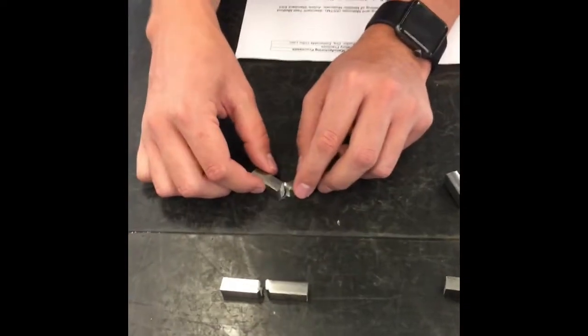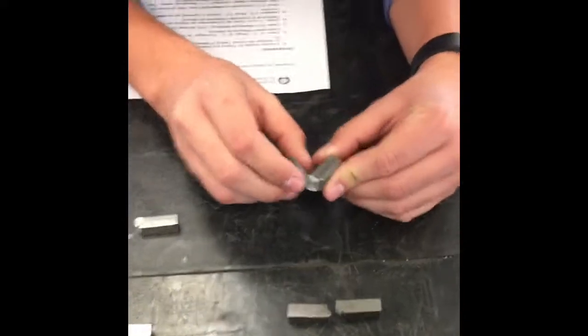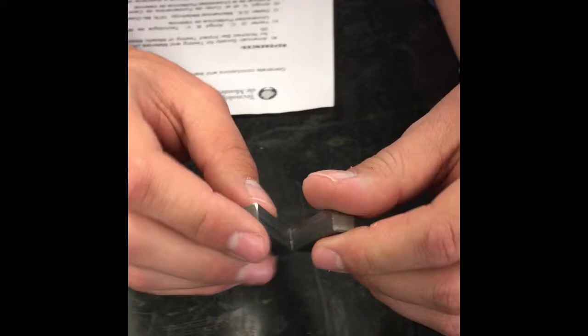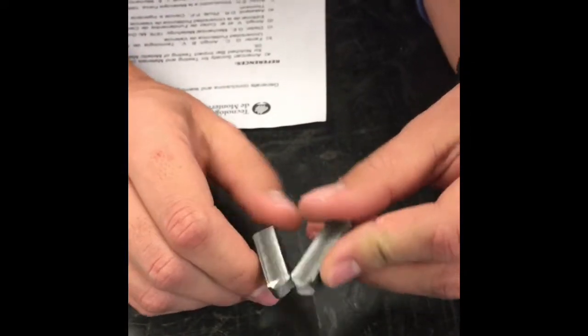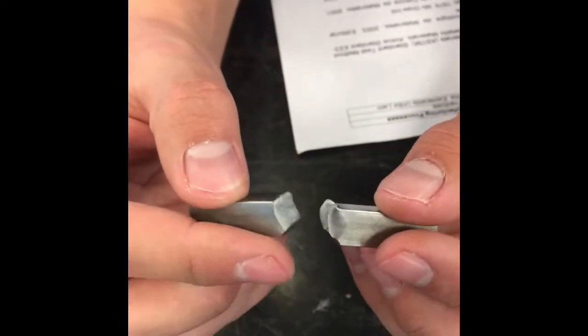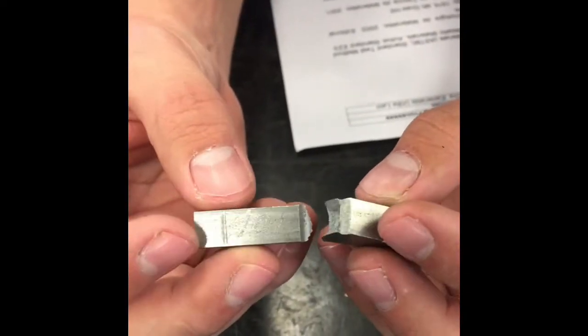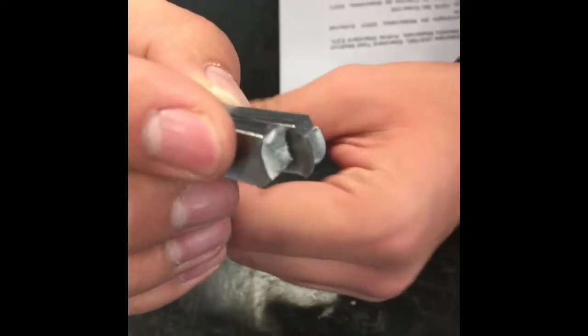ductile fracture. Both of them, you can see it, and especially in this one, which didn't even have a full fracture because it's still joined with the whole specimen. And this one we can see that it had the fracture, and as you can see right here, we are also going to put some photos in the video. It has a ductile fracture, and it's really easy to see the type of fracture that we have here.